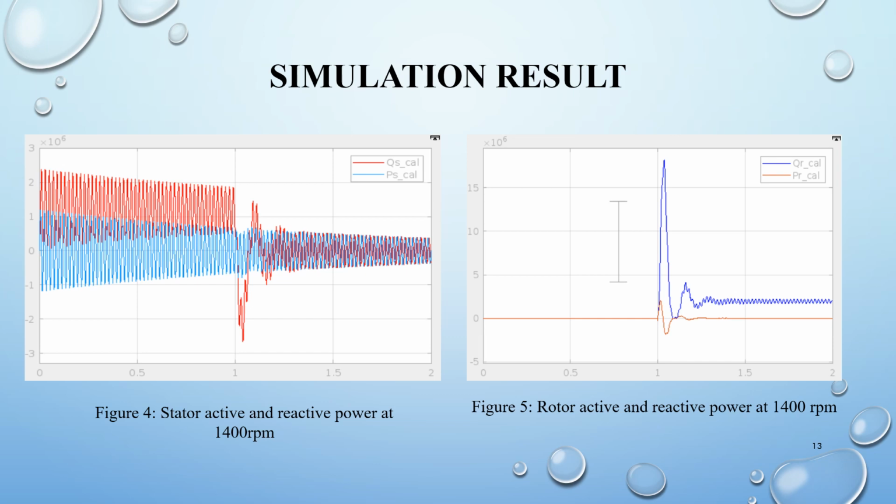At first, no control action is initiated as the machine begins to run for the rotor. The machine will start as an induction motor, draw electricity from the grid, and begin controlled operation after 1 second, when the speed is lower than the synchronous speed. After some oscillation, it will then function as a generator and stabilize at the reference value. For the stator, we can see that there is more fluctuation from the start till 1 second, and after 1 second it will stabilize at some point.